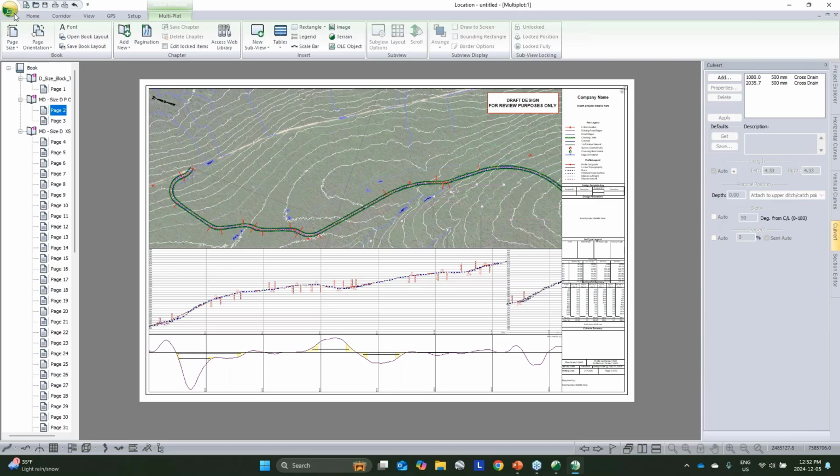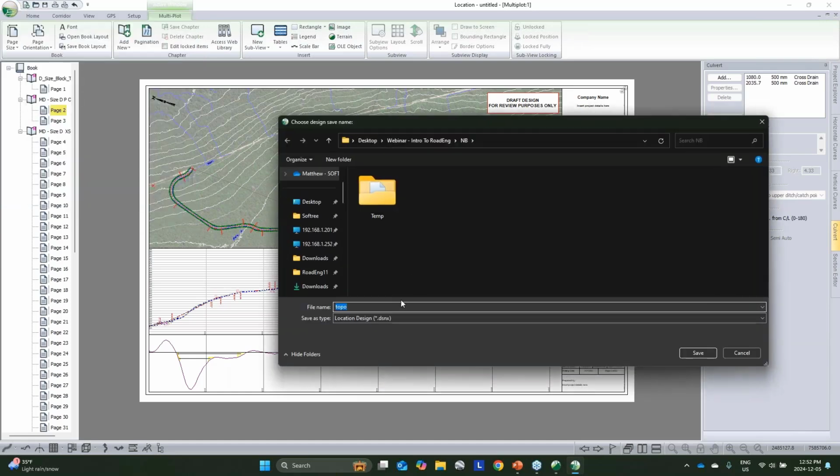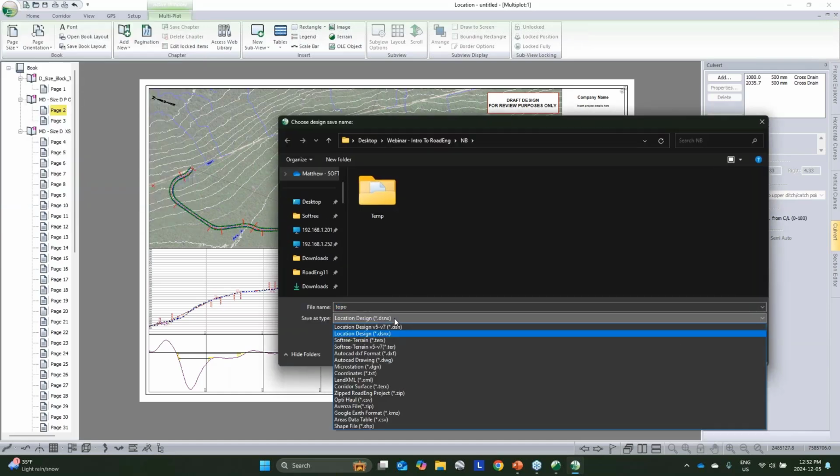If we would rather it in a digital format for construction, maybe construction staking, File, Save As, and we can change the export extension to, well, any number of industry standard formats. So LandXML being an awesome one for cross-platform sharing or construction staking or machine controls. Shape, great to go back and forth with the GIS folks, and other formats, DWG, DGN, DXF are all easily written.